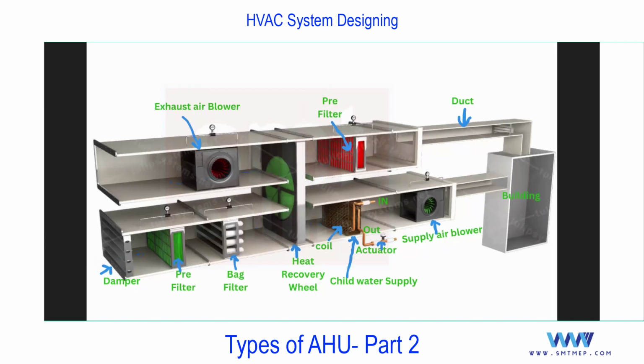Just what is HRU, the heat recovery unit? In short, in the exhaust air, it will give some cooling effect to the wheels, right? And again, when you provide fresh air from the atmosphere, when it passes through the wheels, the temperature will get lower than the outside temperature.